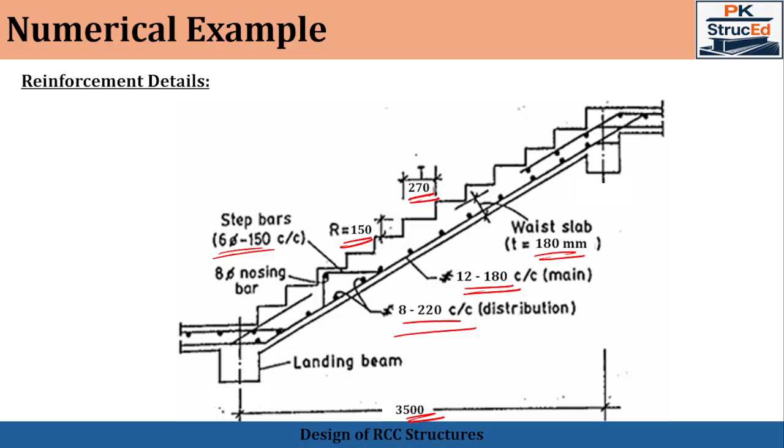Now let us summarize today's lecture. Staircases are designed as inclined slabs. Load calculation is the most critical step, as the slab is inclined and that has to be converted in the form of vertical loading. So the base slab type staircases carry slab weight, step weight as well as the live load in addition to the finishing load. So the design includes flexure, shear as well as the serviceability checks. So proper detailing ensures safety and durability of the structure.